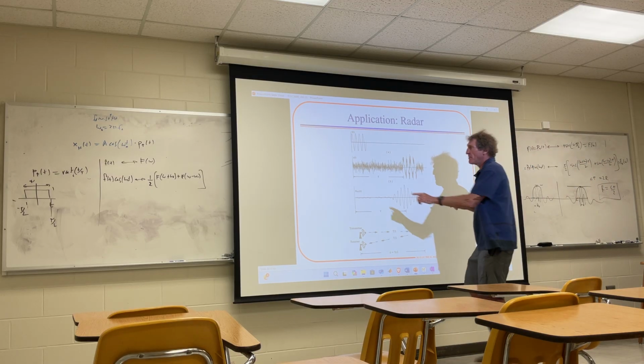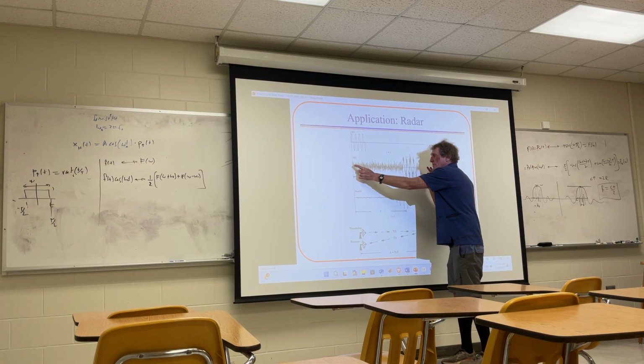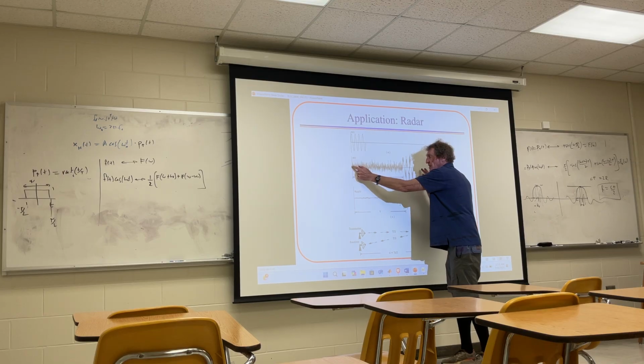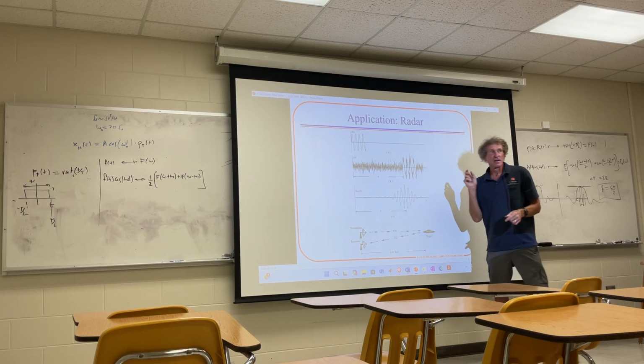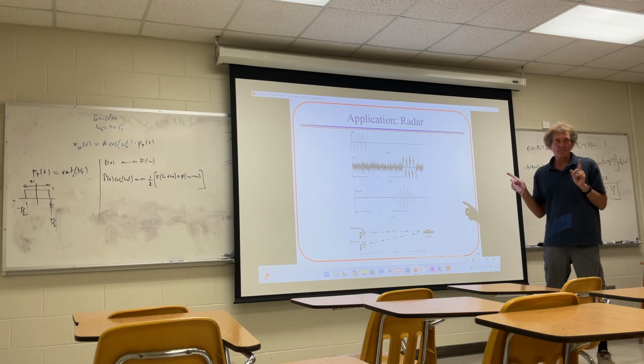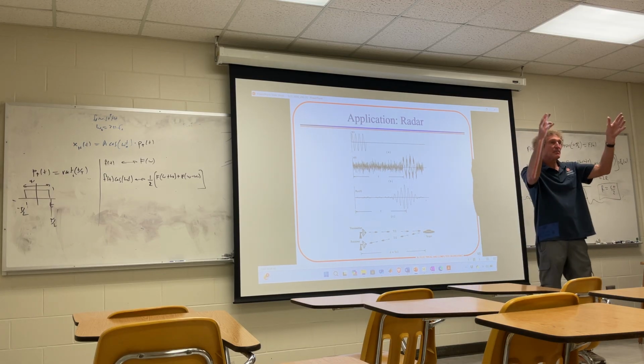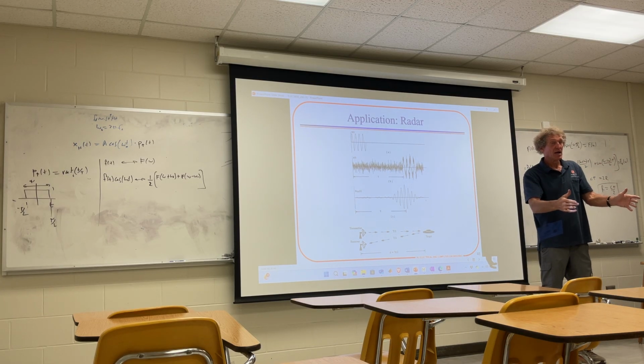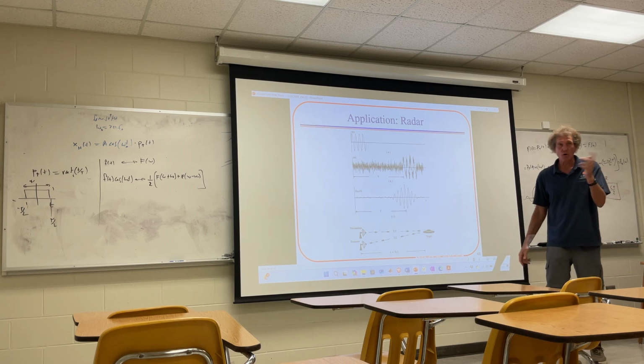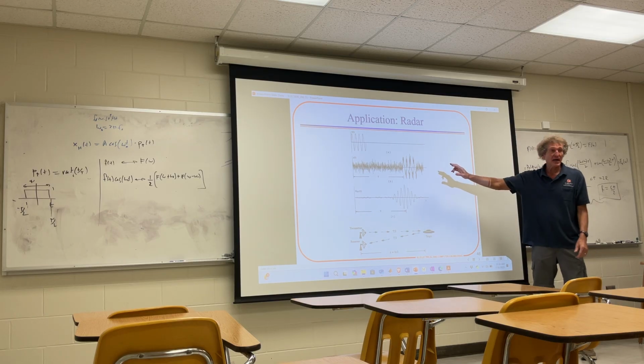I know from the time I transmit to the time I receive this, or basically I start recording everything I receive over a portion of time. Then I take all those signals that are A to D and I add them up. And guess what? The signal will add constructively and the noise doesn't add at all. That's the beautiful thing. You'll get rid of the noise by doing something called coherent signal processing. And that's all it means.